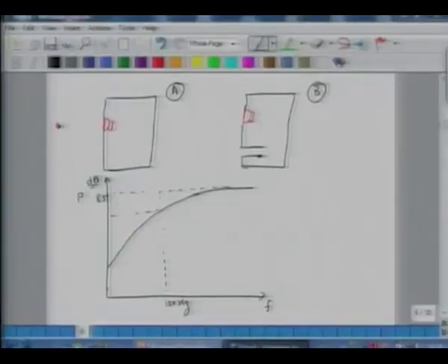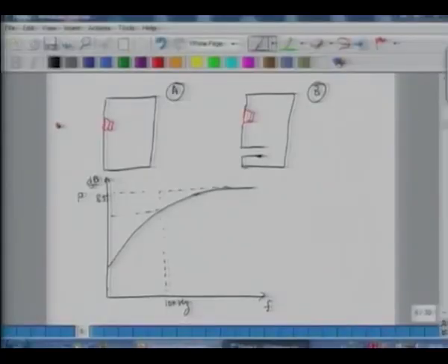6 dB means twice the energy content is 2 times less in the whole system. So if this drop is 6 dB, essentially what it says is that at maybe a higher frequency it's producing 85 dB, but at 100 hertz it's producing 6 dB or even less than that 85 dB threshold, which is not a good thing, which means that low frequencies, bass frequencies, which people like to hear more of, are not being produced at an equal level.